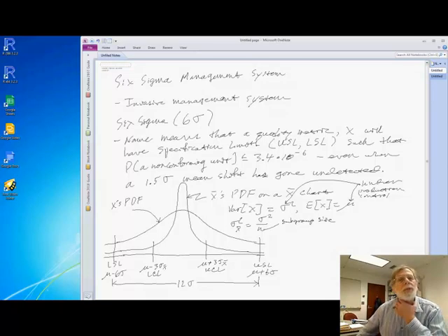And so the point I'm trying to make is Six Sigma is not about X bar, because X bar is dependent upon the subgroup size you've chosen to run. Six Sigma is about the metric itself. If you're measuring a critical dimension and you're using that to build your X bar chart, Six Sigma comments on the mean and the variance of X itself, the raw variable you're measuring, not the subgroup mean.